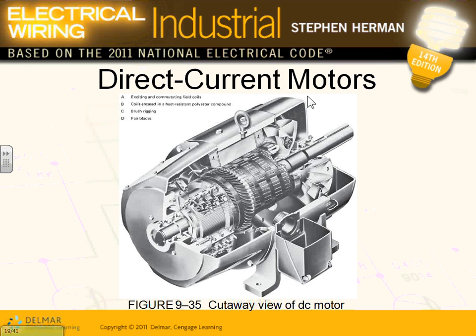You run these babies on DC. When you guys have a DC system, is there a frequency for that? What's the frequency for the DC? There's no frequency for the DC. So if you reduce the voltage, you don't have to worry about the frequency. So easy to control the speed, relatively easy. If you want the motor to run at certain speed, you just tweak the voltage down. So that's the way it became very superior.